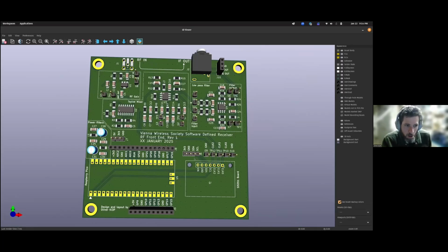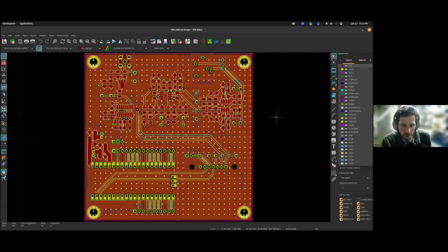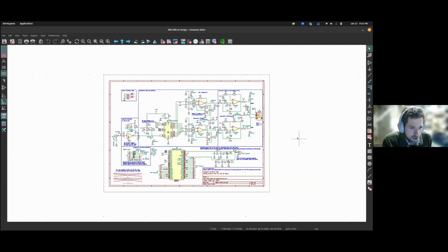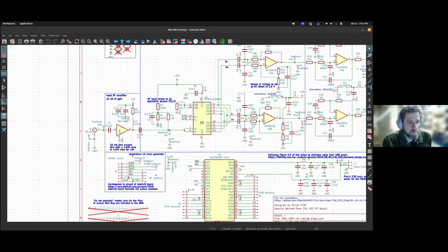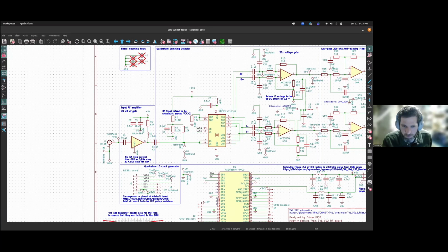So at this point, I wanted to show you something about the workflow in KiCad, that it's not just linear, one way from the schematic coming to here. Let's say we got to this point and we decided we want to change the schematic. What I really want to do is add a component to the schematic, because I don't trust that I'm going to be able to solder the RF amplifier accurately.